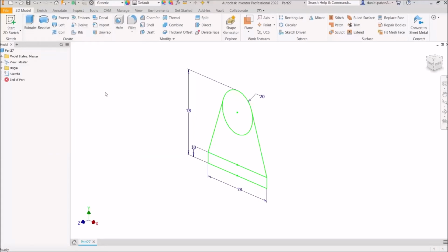The extrude tool is going to allow us to take a closed region, so it must be an area that's sort of watertight or airtight, somewhere where there's no gaps or no openings. And you can see here that all of these are closed regions. There's no open areas anywhere.